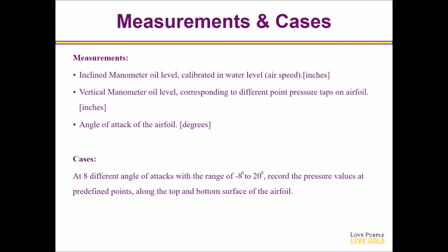In terms of cases, we need to run this experiment at 8 different angles of attack, with a range of -8 degrees to 20 degrees. Later, we need to record the pressure values at predefined points along the top and bottom surface of the airfoil.